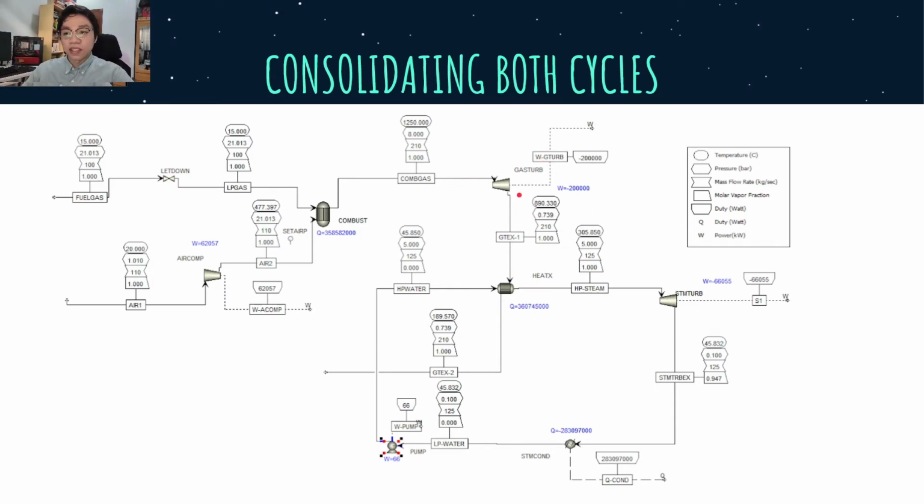Our gas turbine is exhausting 890 degrees Celsius. And we're going to use that 890 degrees Celsius in our heat exchanger to heat our high pressure water at 45 degrees to 305 degrees Celsius at 5 bars. So this is going to give us the steam that we need in order to power our steam turbine.